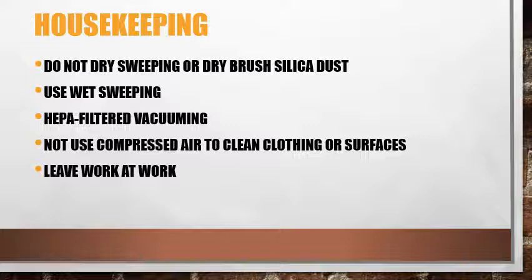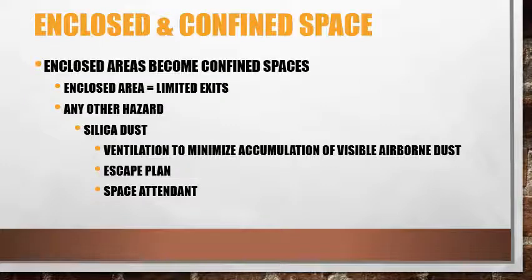Do not use compressed air to clean off your clothing or surfaces, as these will put the silica dust into the air to be breathed and create a hazard. Also, do not use a leaf blower to clean up silica dust, as that would also scatter the silica dust into the air. Finally, leave work at work. Make sure that the silica dust that you carry home on your clothing is removed before you enter your house. Hug your kids, hug your wife. Dust is then released from your body around them.